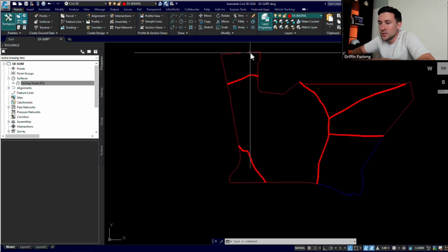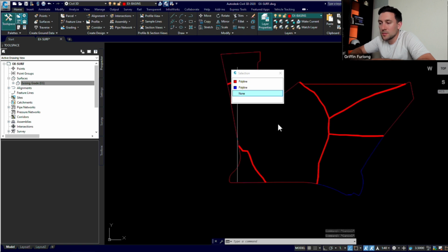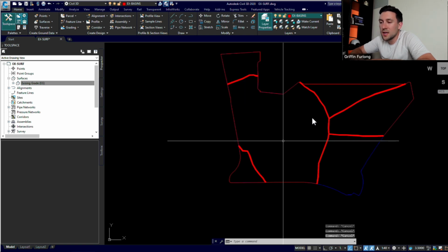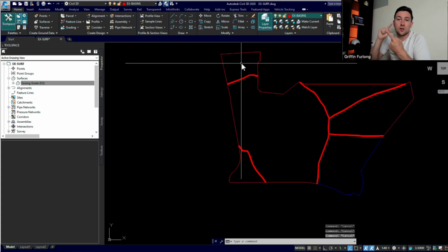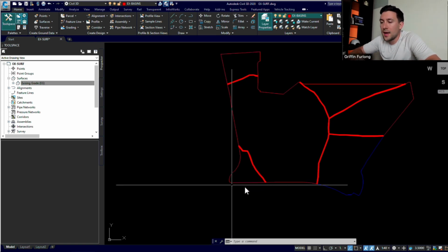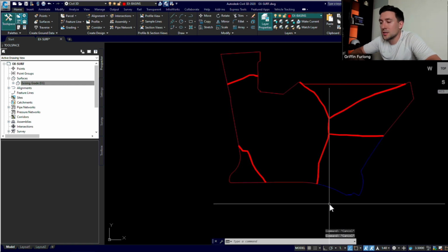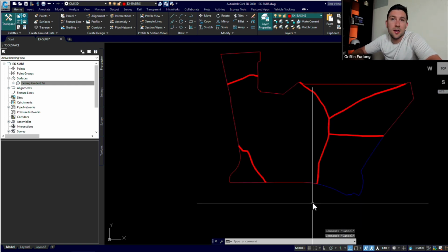And what I would always do is open up a spreadsheet and start making sure and documenting each of your existing basins, because at the end of the day you want to make sure that all of these basins are closed and that you don't have any more on-site basin than your actual property boundary, because that wouldn't make sense. We've used the property boundary as the overall boundary of the project, so we shouldn't expect to see any more basin area or any less.